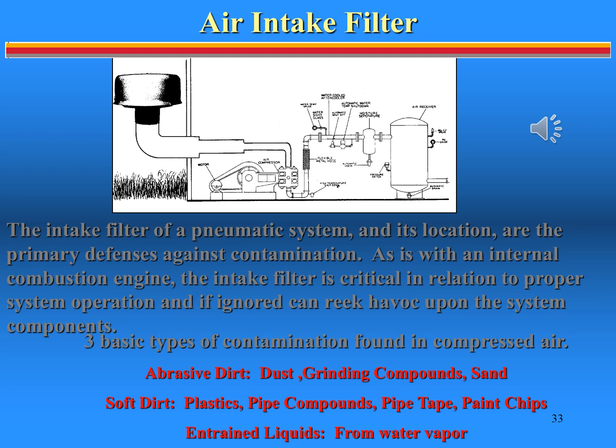Contaminants are produced from any one of three sources. First, as the system is assembled, they may be built in as what happened in a dirty environment. Second, dirt can be generated when moving parts begin to wear. Third, dirt can be ingested by a filthy reassembly practice or through a seal in an actuator working in a dirty environment.